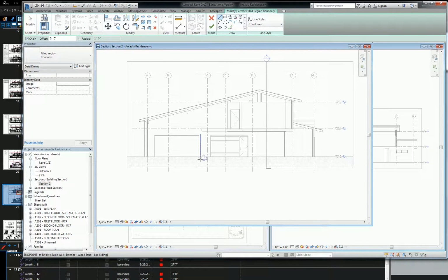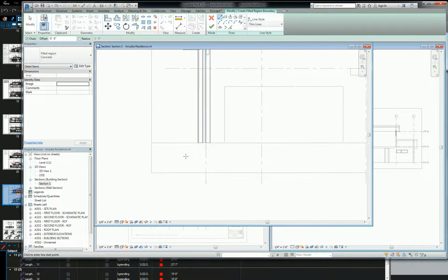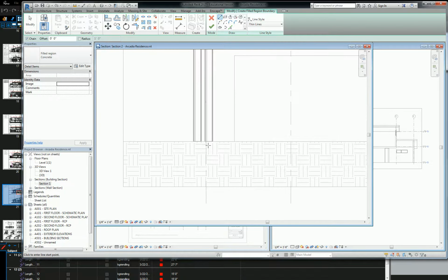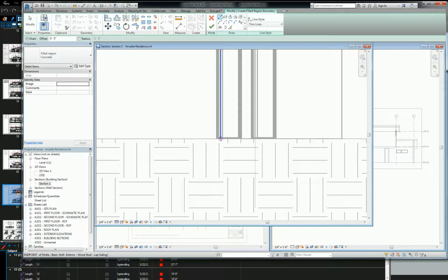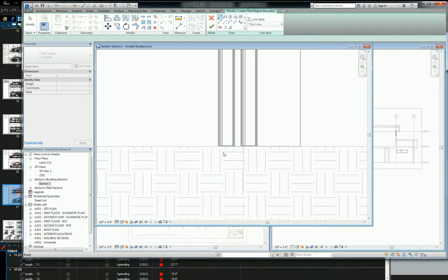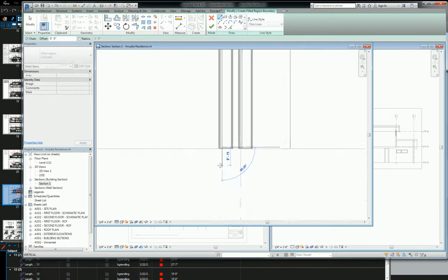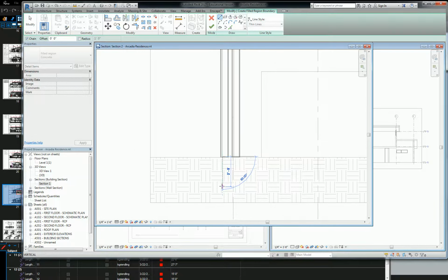And then what we're going to do is go to the exterior most of our exterior wall. That would be this one right here. And we're going to draw from the plywood. The plywood layer right here is your first layer inside. Actually, no, we're going to draw from inside the plywood where the studs go. I'm going to draw a line down about 2 feet to start.